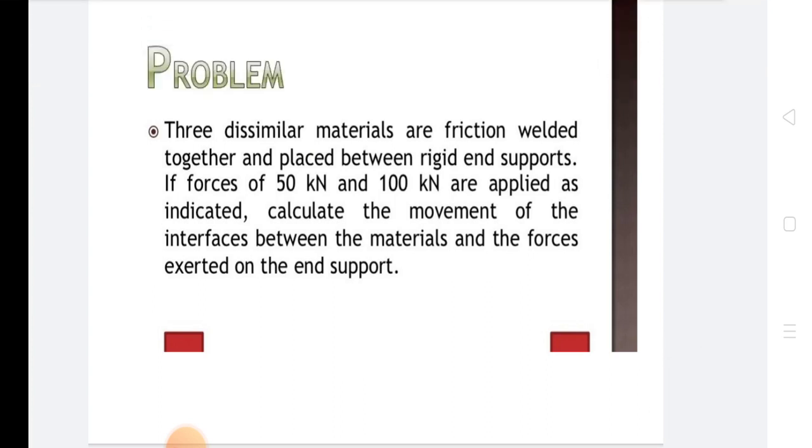In step 3, there is derivation of elemental matrices and load vectors. The elemental stiffness matrix and load vector for each element are derived using various methods such as the direct method and the potential energy method. The equilibrium equation for an element is given as Ke Q = F, where Ke is the element stiffness matrix, Q is the displacement vector and F is the element load vector.